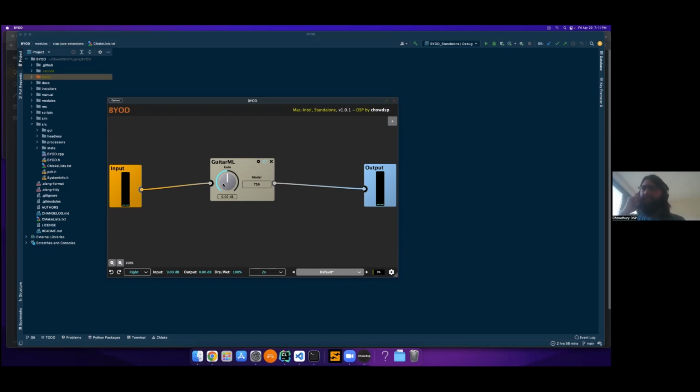But the thing I found more interesting was that as I was looking at these circuits and starting to understand them more, I noticed that a lot of them had very similar little parts. Like there was a configuration with the op amp where you have a feedback loop with some diodes in it, and that's kind of the Tube Screamer circuit. Or there's a diode clipper circuit where you have some signal and then a diode going to ground, and maybe you've got 3 or 4 diodes, depending on the circuit. Or there were various tone circuits that seemed to come up quite commonly as well.